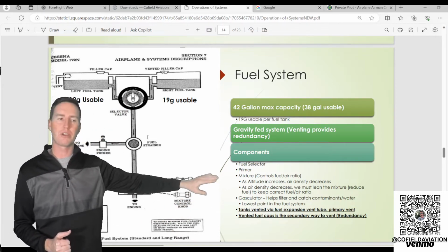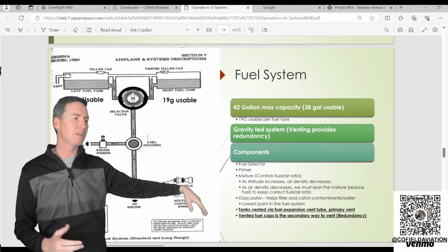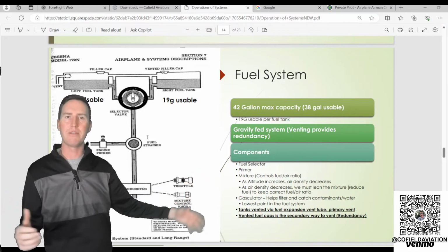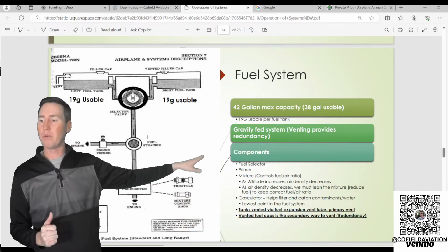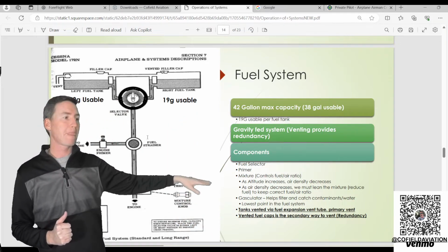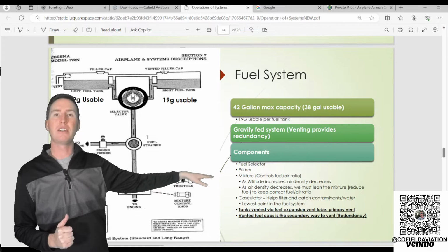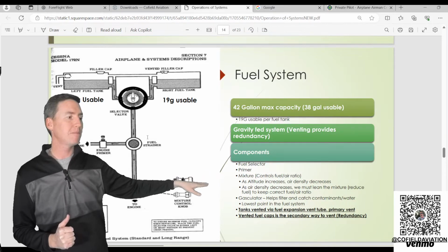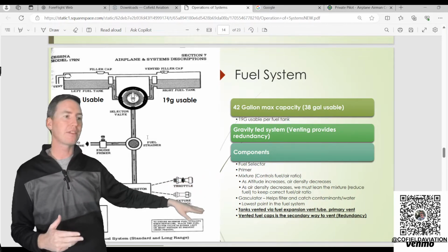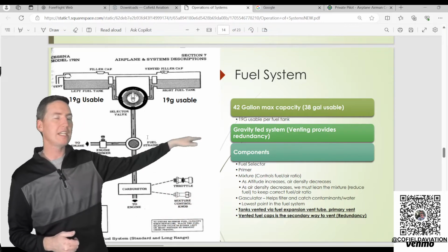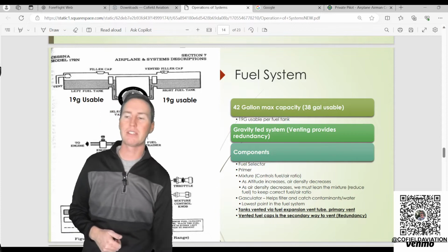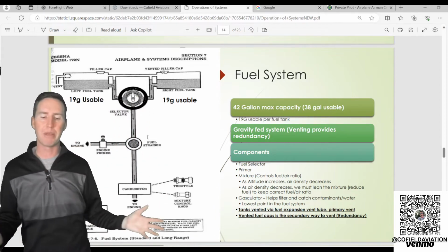So the easiest way to do it is note your exhaust gas temperature. Whichever one is your hottest, just go by the hottest EGT, whether it's 1400 or 1350 or whatever it is for your engine, and literally just keep that all the way up. Let's just say it's 1400 at takeoff. As you climb, it'll go down to 1380, 1370, 1360. Just start leaning it back to bring that EGT back to 1400. If you have an EGT gauge, that's the best way to do it.